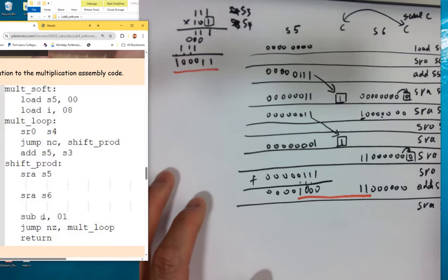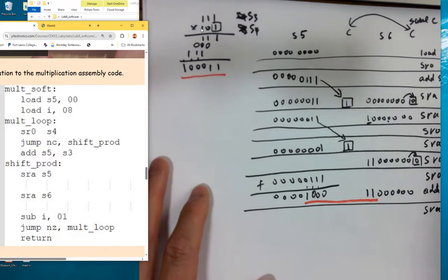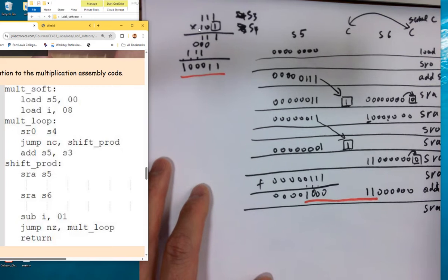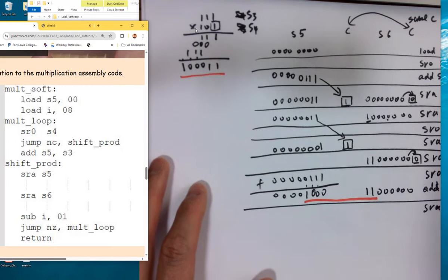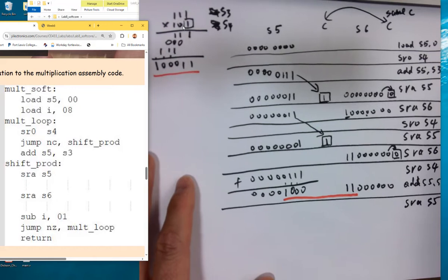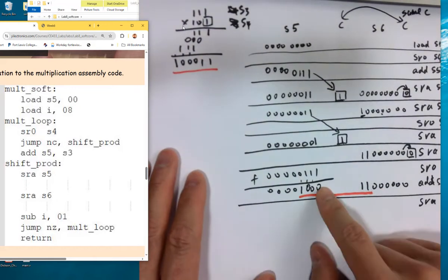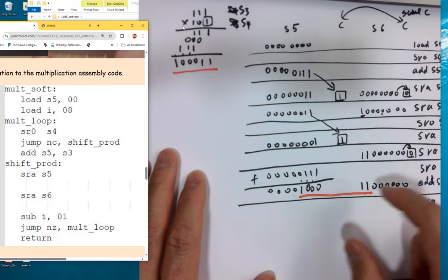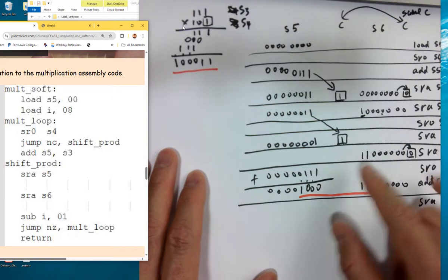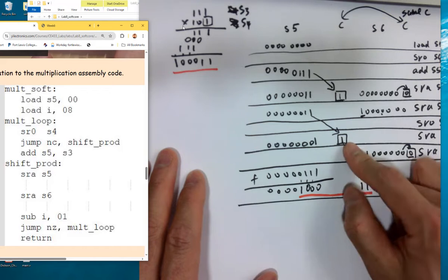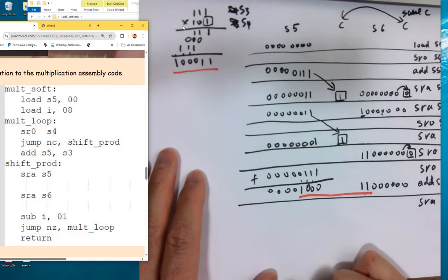So it's still gonna shift everything to the right. And the thing is, the multiplier, all the 0 bits in front of it are all zeros. So whenever after shifting this MSB of the multiplier out, all the following multiplier bits will be all zeros. So it's basically not adding anything to it. So whatever this guy is doing is just purely shifting. It shifts the LSB to C and gets that C to the MSB of the lower byte, and eventually everything got shifted, using the C as a buffering bit, but nothing else.